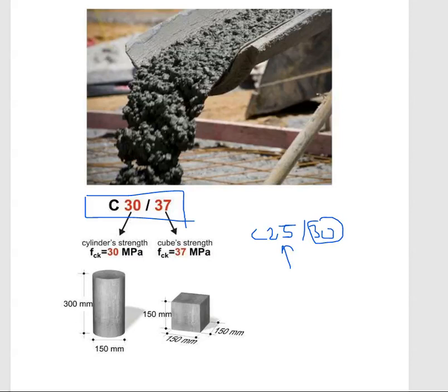An example: imagine two slabs, both using the same concrete mix. One slab is cured properly for 7 days, the other slab is left dry in the sun. The cured slab will usually be much stronger and more durable.